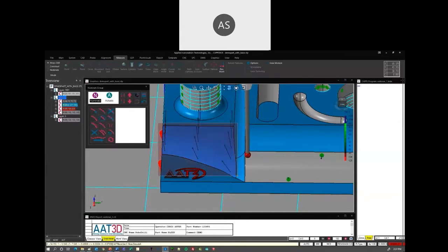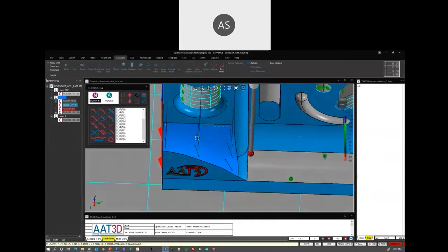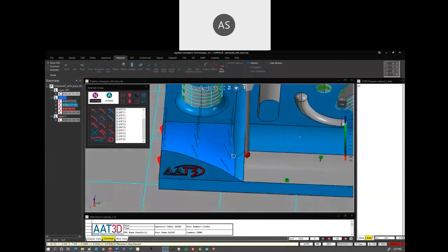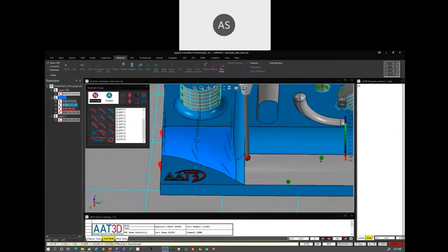So we'll just box this in. You can see here the system generates the movement path for me, starting at the sphere here and moving through the points like that. So there's the path that the system's going to follow. Okay, if I'm happy with what I see, now let's say I wanted to go the other direction, I could simply choose one of these options here to change the order in which the points have been selected. I can pick a point, move it up and down the list. I also have an optimization function here, which will try and generate the shortest path through all the points. Okay, but we're just going to use the order that the software came up with here.